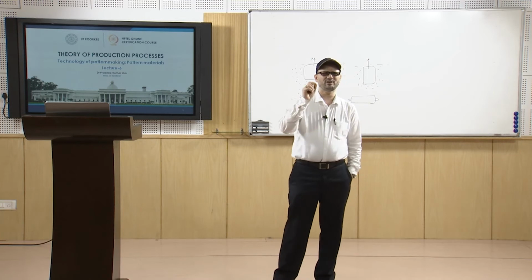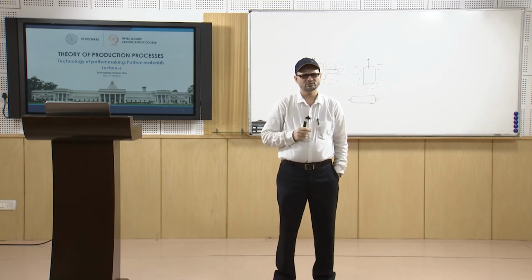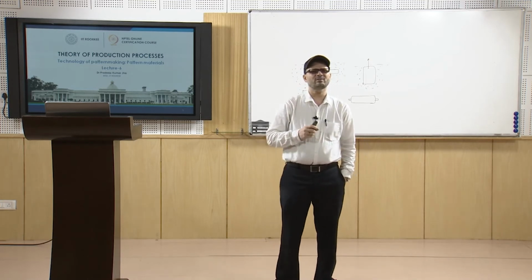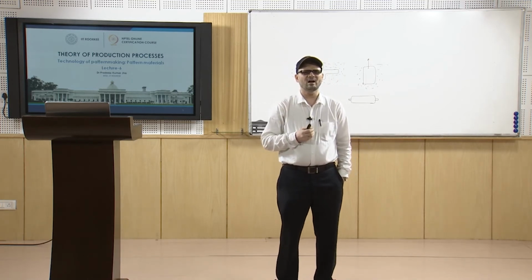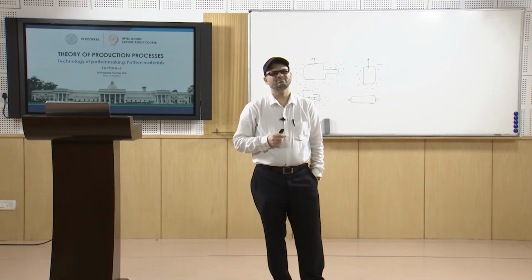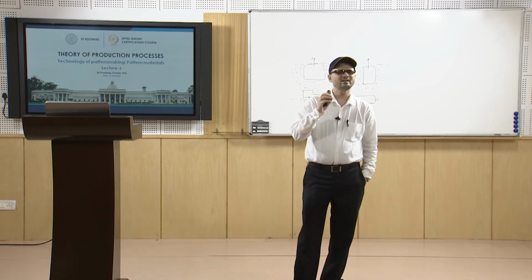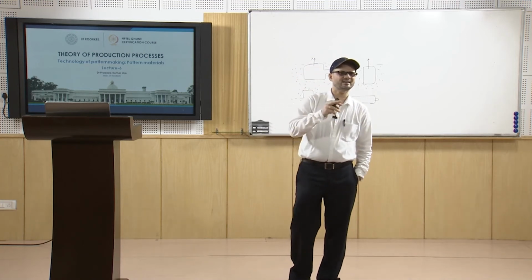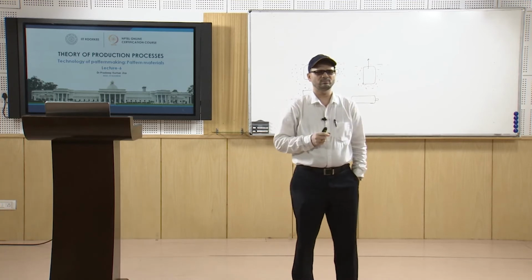Among the natural woods, mahogany is said to be the best choice for pattern work. So, we prefer the mahogany one. It is ideal where the number of castings required is quite large, because, as was said, mahogany is hard and strong as well as durable. So, when you have to go for a larger number of castings, this is quite suitable.